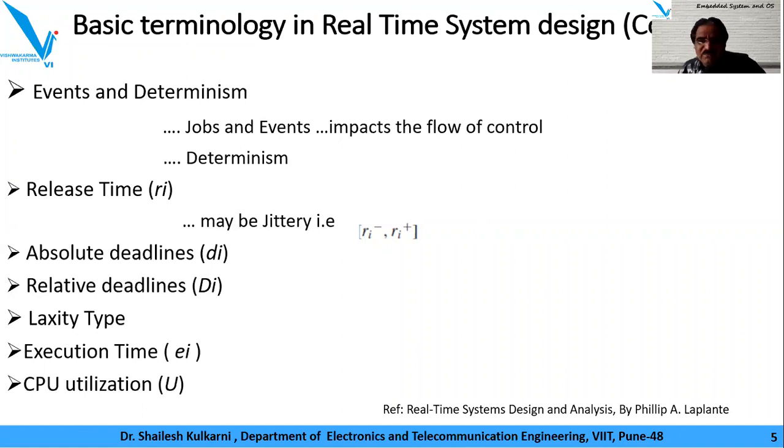There is no relaxation in the timing of execution given for it. As against that, relative deadlines say that there happens to be some kind of relaxation given in tandem with the task on which it depends. The word itself, relative deadline, might be easy to understand. I have the very stringent deadline that I referred to as the absolute deadline within which a task has to execute.